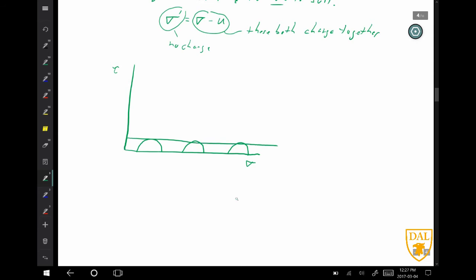Okay, so that results in a more or less perfectly flat failure envelope. So the undrained friction angle is zero. And so it's often called a phi equals zero analysis.